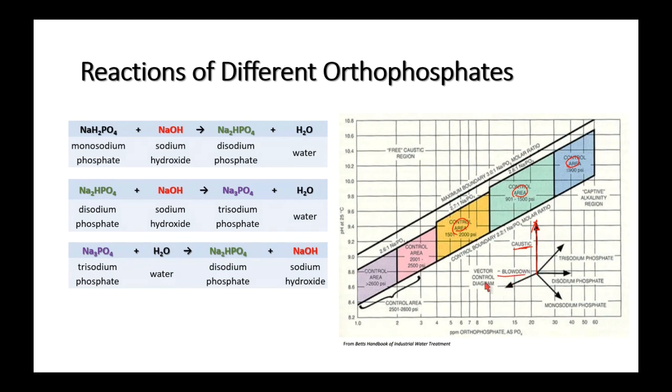And blowdown is also shown on this vector diagram. Blowdown has an effect because it dumps water from the boiler, right? So if it's going to dump water from the boiler, the blowdown, and again resolving this into vectors, is going to lower the phosphate, and it's also going to lower the pH. Just because we're getting rid of this stuff that's in the boiler and replacing it with fairly pure water in our makeup.